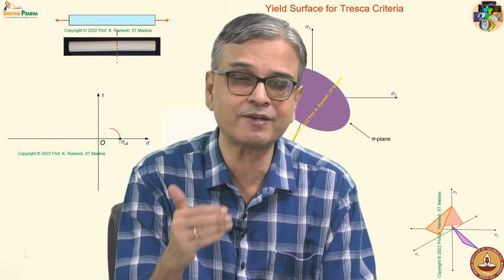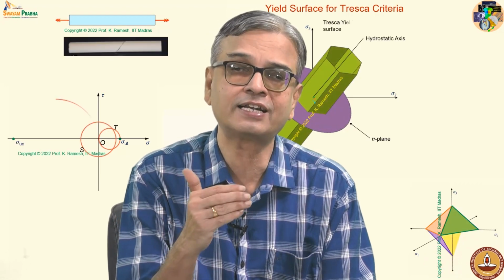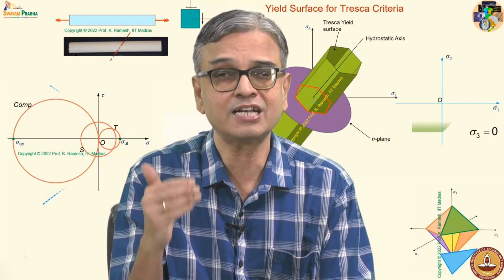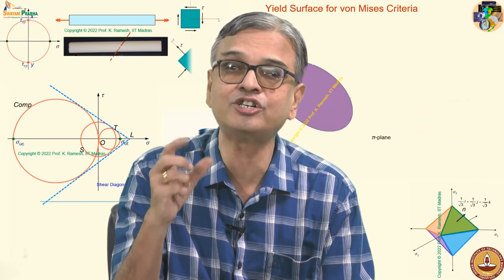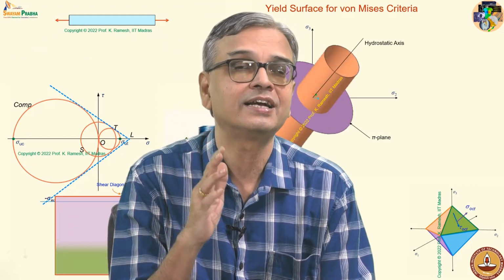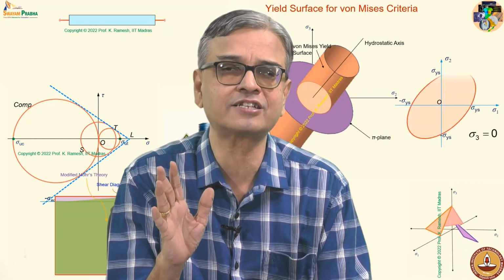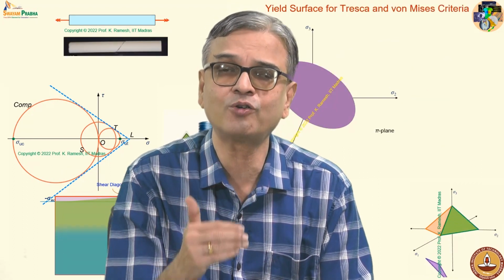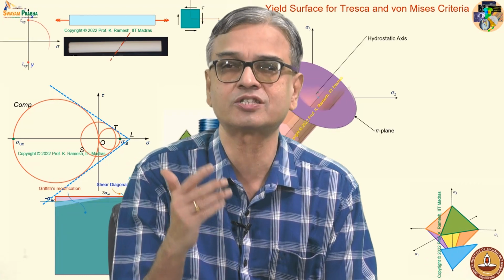So, in the case of brittle materials, we have seen only the simple maximum principal stress theory, and for ductile materials, Tresca was the oldest, and distortion and octahedral merged into one. So, you have two theories now for ductile materials, fine, and we will continue further in the next class to find out a better theory for brittle materials and also solve some problems.